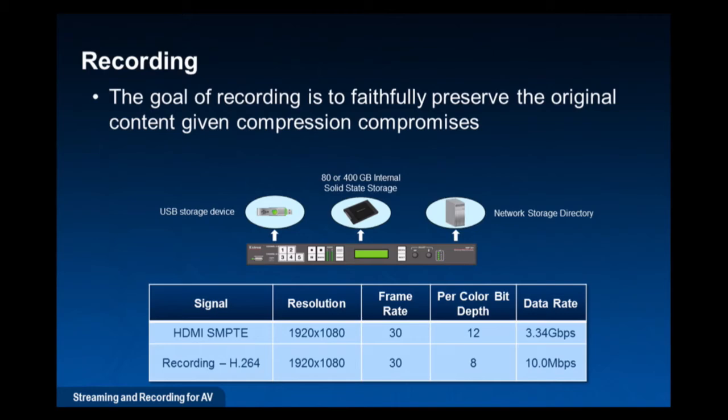This information is also available on our website, but take that basic video cable. I talked about running my HDMI cable from my laptop or the Blu-ray or whatever. As you see on here, it's basically a 10 megahertz video signal. So take your 100 meg, your 1 gig video network, and you want to start dropping 10 megs of video chunks on it at a time. The IT guy is going to raise a flag or needs to be involved way early. So hopefully I'm giving you some information and some thought process to talk to those about.